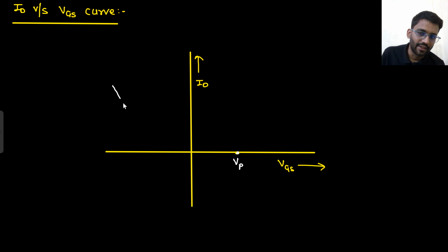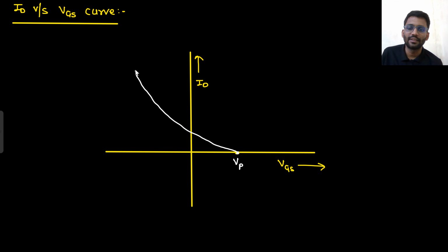I hope you have already understood because we have spent a lot of time understanding the N-channel depletion type MOSFET. This is just the opposite of that, nothing else. Right? So this is the N-channel, this is the P-channel depletion type MOSFET. So if you increase the Vg in the negative direction, the current will increase. And what is the direction of current? The direction of current is from source to drain. Understood? All clear? So in this lecture, we have studied depletion type of MOSFET.